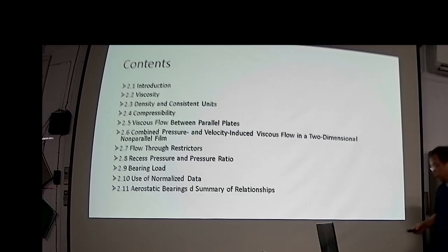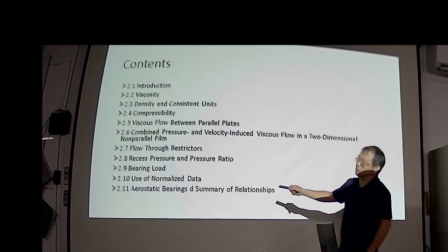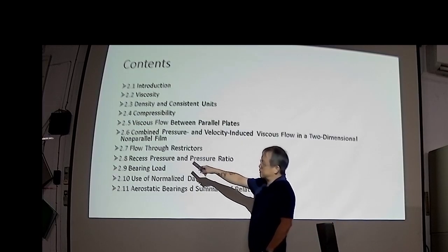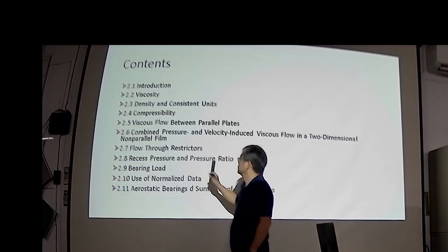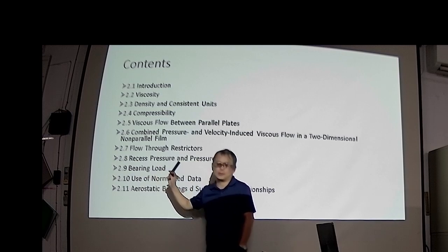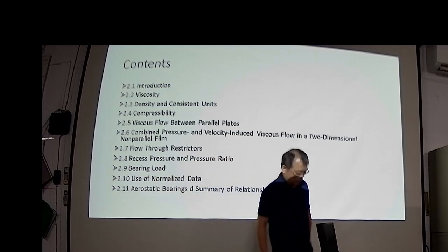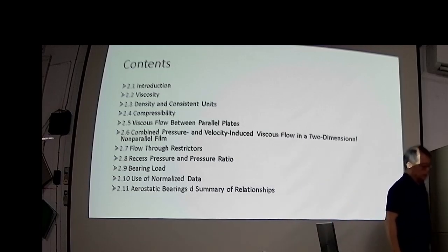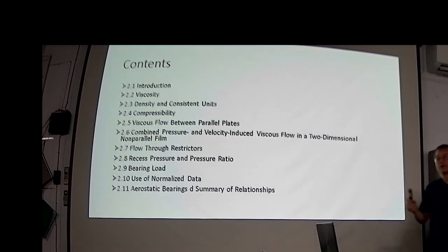So this is the important thing. You know how to calculate the recess pressure, and you can calculate the bearing load capacity, because that is the key for you to design a hydrostatic bearing for application in machine tools.